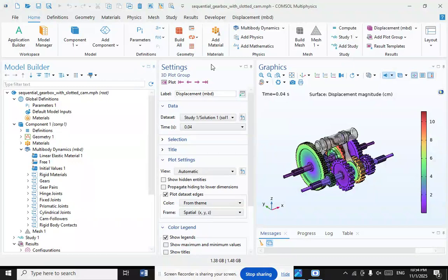Some transmission designs, such as in the Volvo 850 and S70, have two counter shafts, both driving an output pinion meshing with a front-wheel drive transaxle ring gear. This allows for a narrower transmission since the length of each countershaft is half compared with one that contains four gears and two shifters.